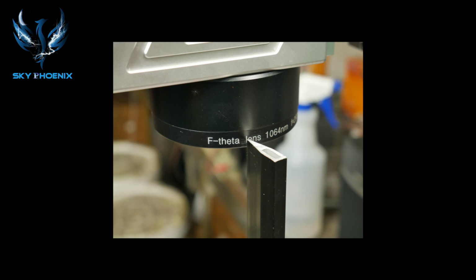And in this video, you'll hear the difference in the burning where I go past the focal point, both too low and too high, and you kind of find the midpoint where it's burning the loudest and you can hear it's the most aggressive. That's your prime focus.